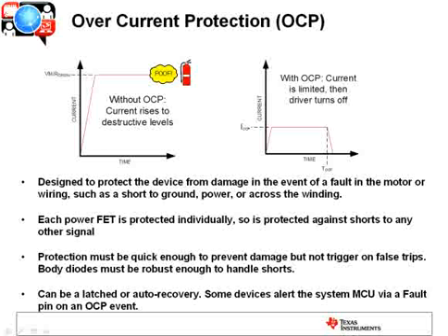Okay, so probably the most important protection is overcurrent protection. You've got pretty high supply voltages. These motors inherently have low winding resistance, and you're always worried about the potential for shorts, some type of short to ground, to power, or across the windings. So you want your motor driver to be protected.